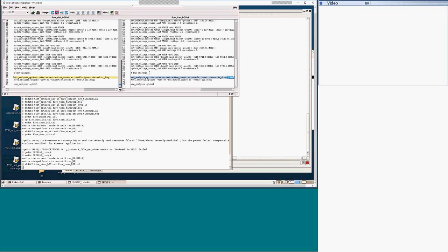Also for a static run, we report average voltage drop. You may have a voltage drop profile, but for a static run, we calculate the average and report just the average. So you can easily overlook peaks in voltage drop. But static is pretty fast, and this is a good estimate of whether your design has any severe IR drop problems.